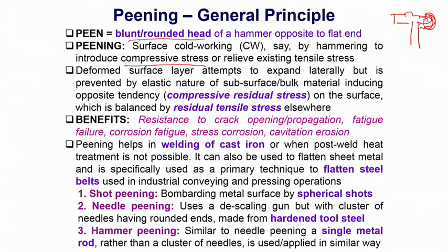So, this is the principal theme of shot peening, that you apply limited surface deformation and the material deforms only up to a very limited depth, but during the process of recovery, a certain amount of state of stress is created, which is residual in nature. That means when you have removed the load, that particular stress still remains, and that stress incidentally is of compressive nature, which is beneficial for very many mechanical applications, or applications which are actually subjected to various mechanical deformation.